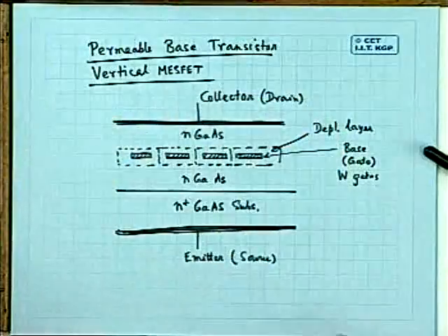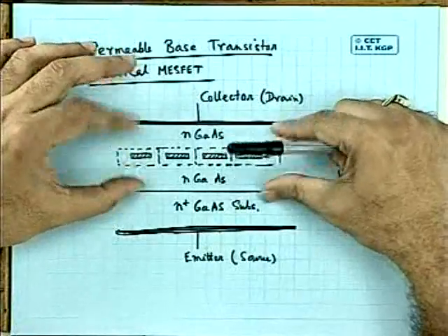This is a very complicated structure, and it was very interesting academically, but did not come to be a very successful one commercially. But it has certain merit. Can you tell me what is the merit? Because the structure is vertical, you can have these thicknesses extremely small. Otherwise, in gallium arsenide, which is a horizontal structure, the only technique of defining distances is by lithography. But here it is a vertical layer. The epitaxial films can be grown to very small thickness. Therefore, one can achieve very high speed.